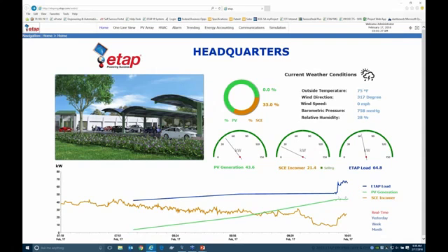And you can actually see right here, around the time somewhere in the middle when the webinar began, the load essentially went up while we were going through our other discussions. And that's essentially the air conditioning that's coming on because we're approaching 10 to 11 a.m. The outside temperature is past the set point of the thermostat, so that's actually triggering certain air conditioning within the building.